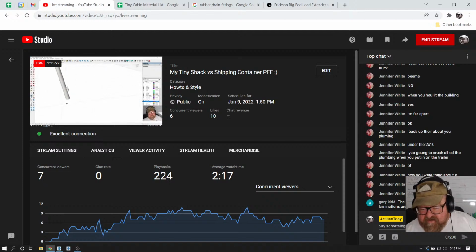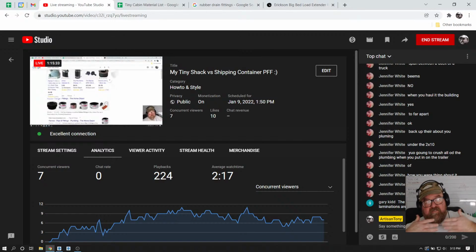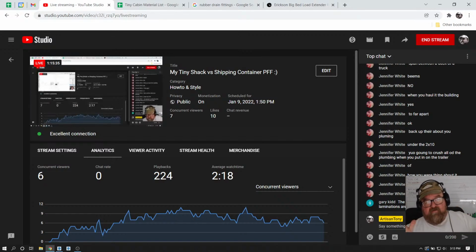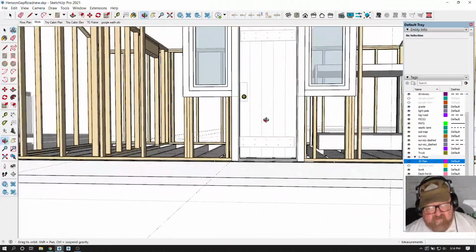Sorry, the beams are site-built laminations, aren't they? Yes, that's why I was talking about the different layers. One layer would be two 12-footers butted together. The next layer would be a 12-footer spread evenly on that joint with two 6-footers on the end. It's kind of like how we build a floor girder. We lap the joints on floor girders, so the joints never all line up. If there are two or three different 2x10s, none of them line up with each other. I should have drawn that, but I didn't.